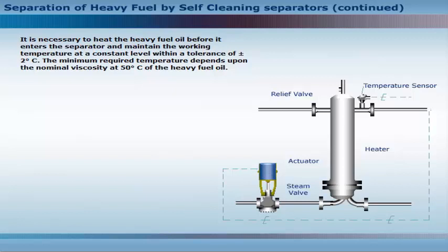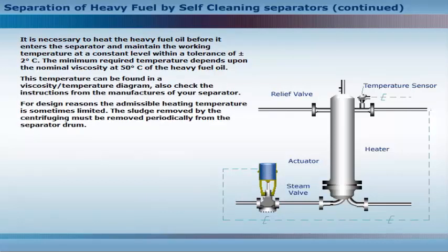The minimum required temperature depends upon the nominal viscosity at 50 degrees Celsius of the heavy fuel oil. This temperature can be found in a viscosity temperature diagram. Also check the instructions from the manufacturers of your separator. For design reasons, the admissible heating temperature is sometimes limited.